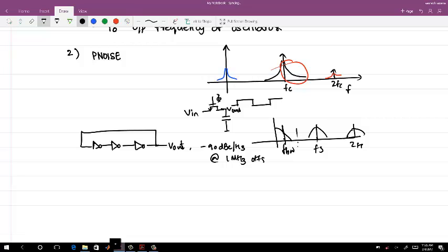This is what I designed, but I find that this is not meeting my final jitter requirements. So I need to double the power, or I need to reduce the phase noise. The easier way is, if I double the power, my phase noise goes down by 3 dB. This we will get when we do the actual ring oscillator phase noise analysis. So in simulation, I made it minus 93 dBc per hertz, and I again do my final jitter calculation, and I know this is going to cost me 2 milliwatt of power.